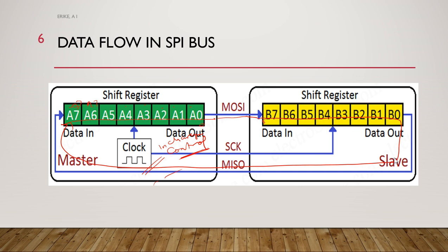So in the buffer register, I said that the clock signal is generated by the master and it controls that. Then in the diagram, the buffer register is actually omitted. So if we need to transmit data, we need to write to the buffer register first, and then it will automatically be written to the shift register when it is free, and the transmission will start.